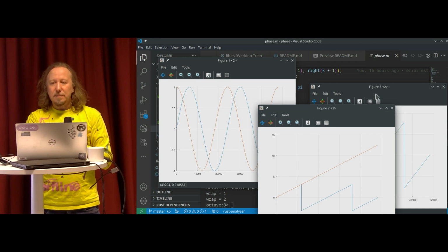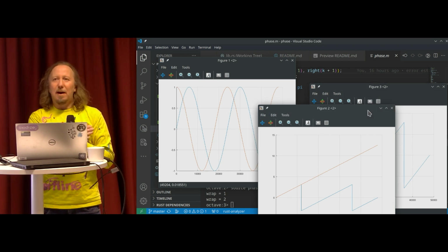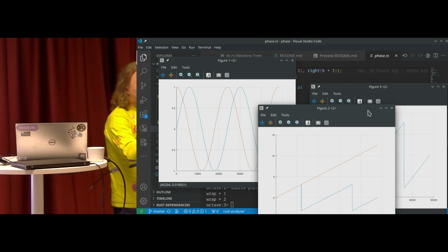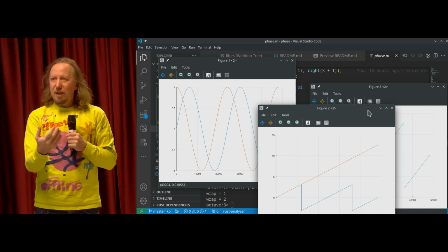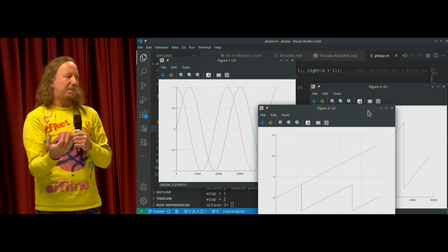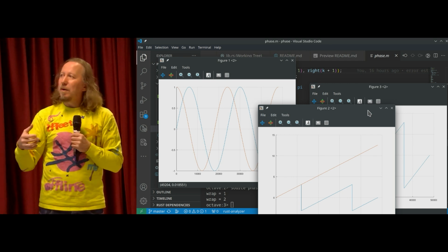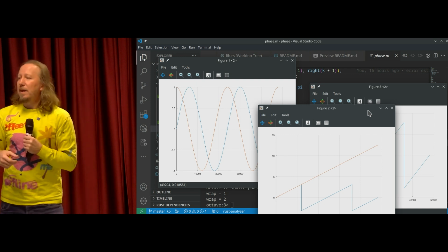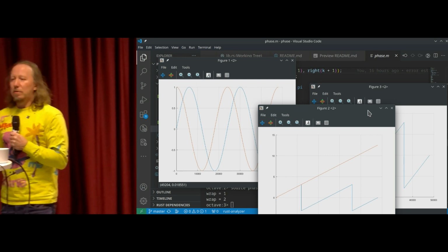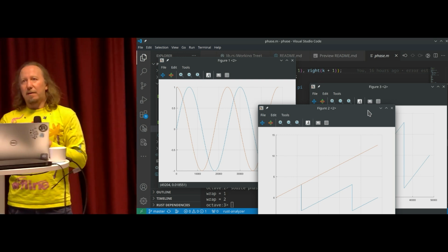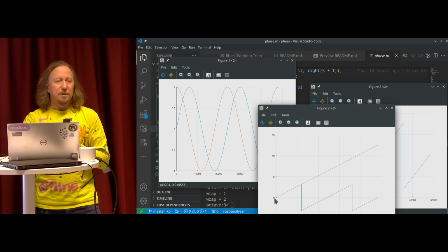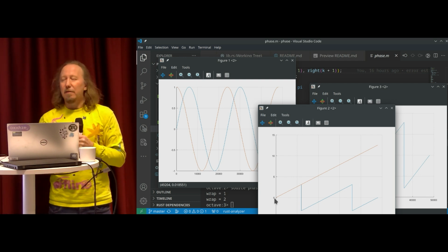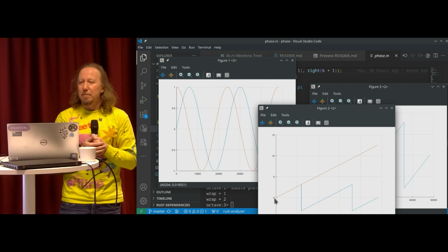Right. So you get the basic idea how this works, that on the vinyl we have these two sinus and cosinus signals. We read them through a sound card. We just sample the signals, and we detect the phase of it with an atan2 function, and we unwrap into an absolute position. Well, absolute in relation that we know the start position, but in general it will be a relative position. But the idea is the same.